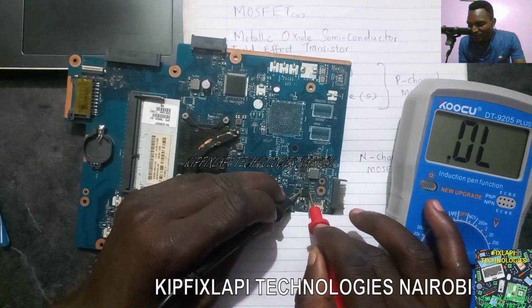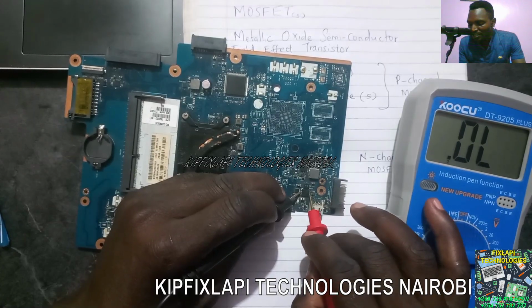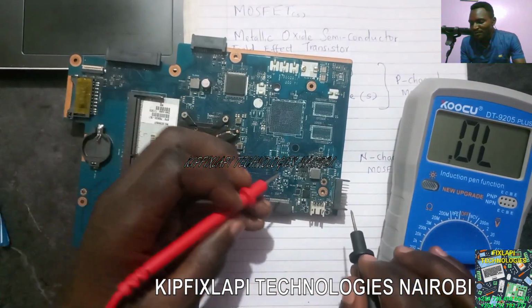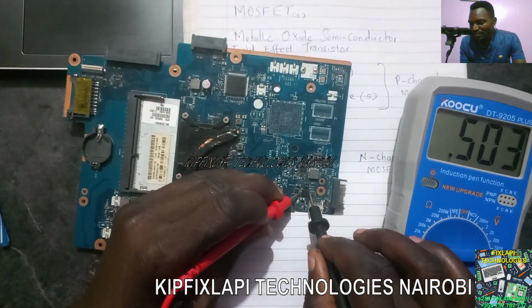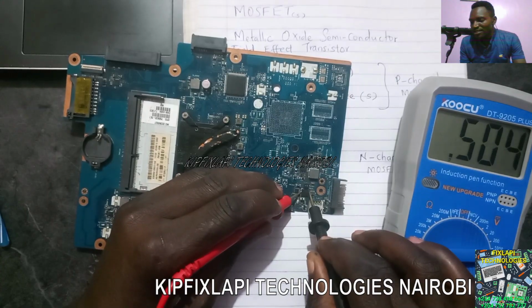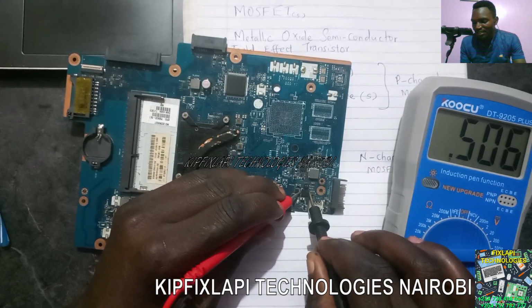You see, guys. When I press it this way, I'm not hearing any beeping, or seeing any readings which show there is a short. I can interchange the probes. When I interchange the probes, you see there is some resistance, that is 0.503 ohms. So that point is correct. There is no short. The source and the drain are not connected.